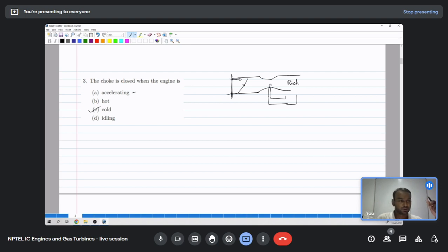So this choke, I think you cannot see in BS6 engines, but till BS4 engines, which were carbureted engines, most of the two-wheelers with BS4 or previous vehicles used carburetor SI engines, and you may have seen a choke knob on the handlebar or somewhere near the engine. So that is used when the engine is not starting during the cold conditions.